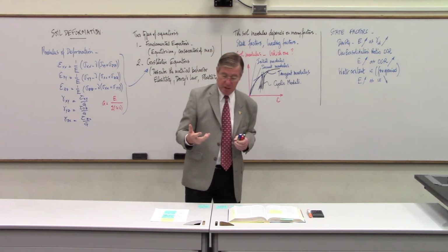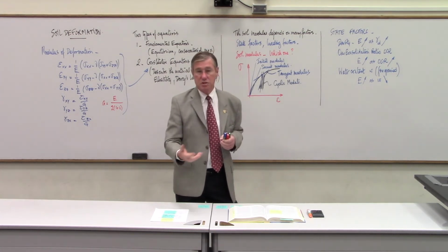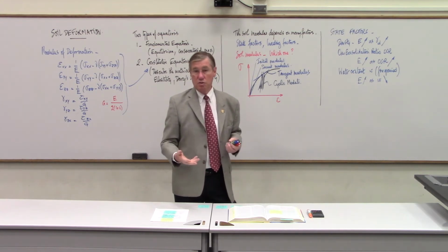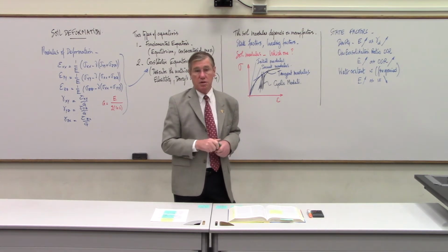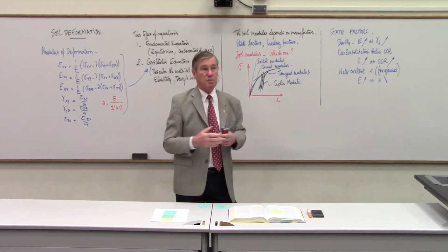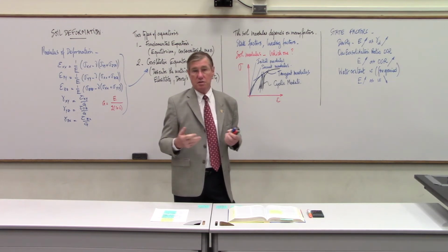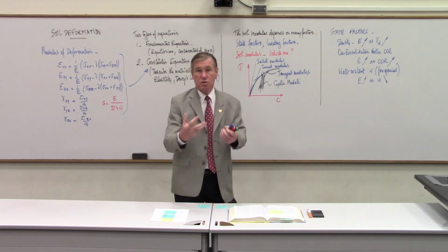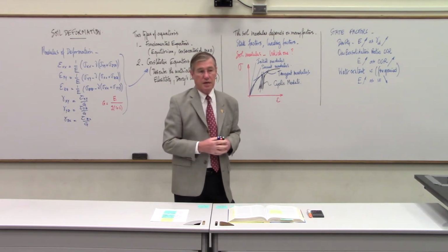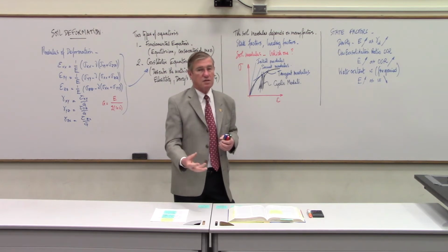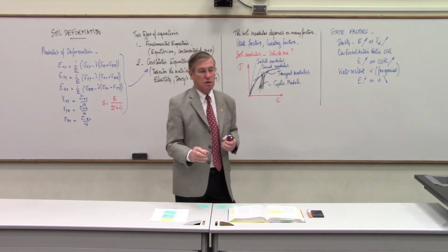We talked about the fact that if you take a piece of soft clay and you put it on the table, and then you come back tomorrow, it's going to be a lot harder tomorrow. Why? Because in this room we have air conditioning, so we have about 50% relative humidity. There's a lot of room for the water to go into the air. And this low relative humidity is attracting the water that's in the soil.